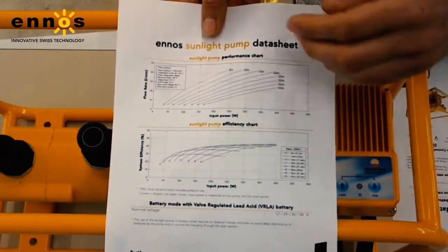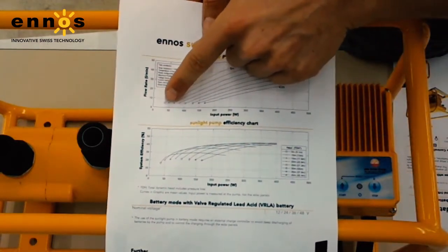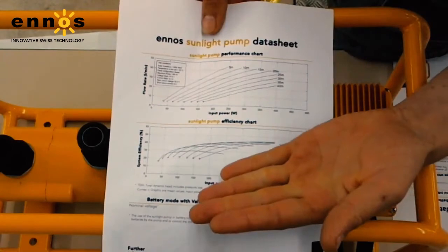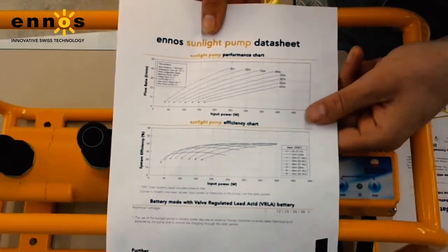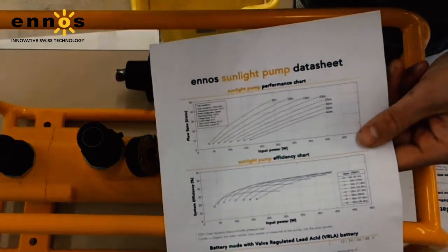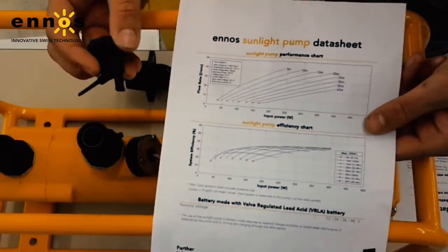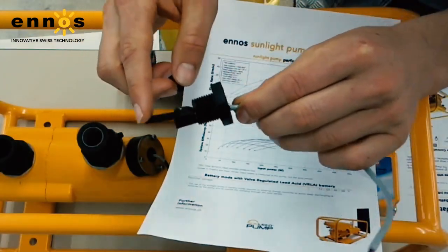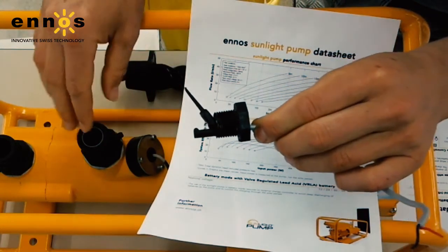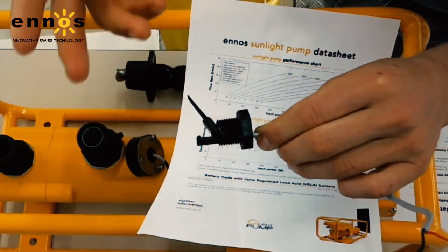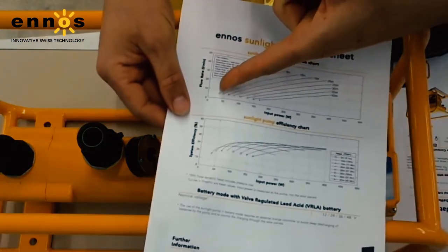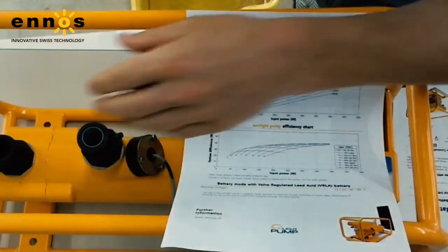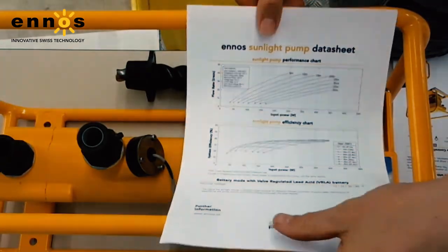One thing I forgot to mention on the above table, you see that the cutoff point is at about 5 litres per minute. So if we fall underneath 5 litres per minute, you need to be aware that the water flow switch, which I mentioned before, will be deactivated. If it's activated, this means water is flowing, and if it's deactivated, this means the water flow is stopped or has fallen underneath our required 5 litres per minute, and then the pump will stop by itself to prevent damage to the pump head mechanism. Good.